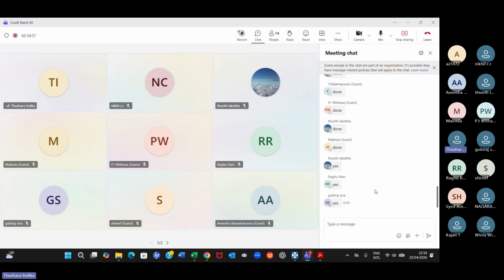If you just summarize it, if you have a rate library in Excel format, you have to just convert it into a CSV file, and then you have to import that CSV file into CostX. Simple as that, through the system admin, and then drag and drop.